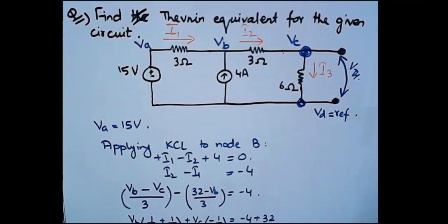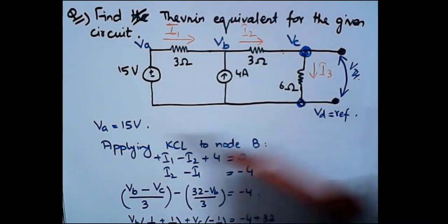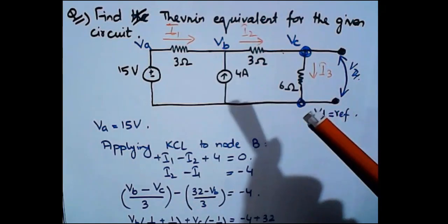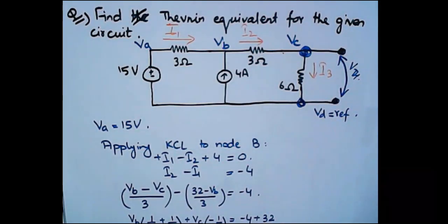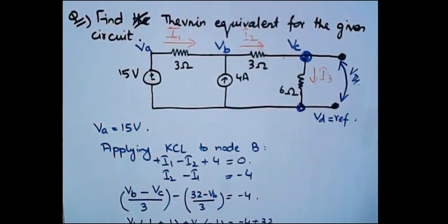We were given this question, and the objective of the question was basically to find the Thevenin equivalent for this circuit, right? And we can see that this circuit was a comparatively complex one with a load at this end, and then there were sources involved, right? Whenever we are required to find the Thevenin equivalent model, basically we need two major parameters: the source resistance, the Thevenin resistance, and the Thevenin voltage.